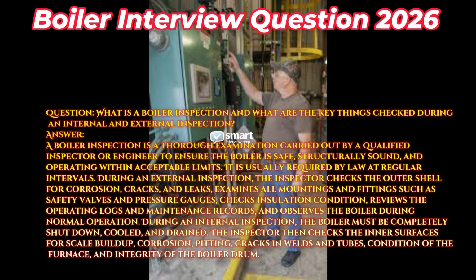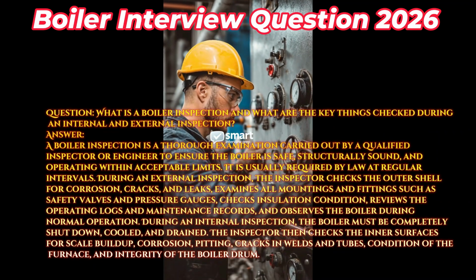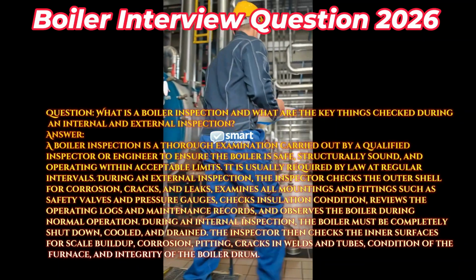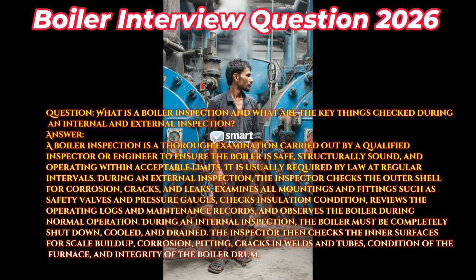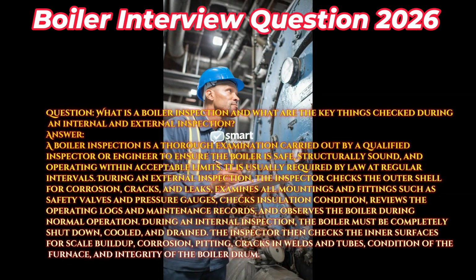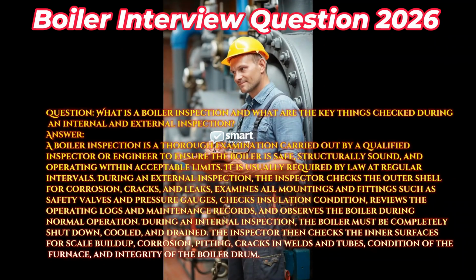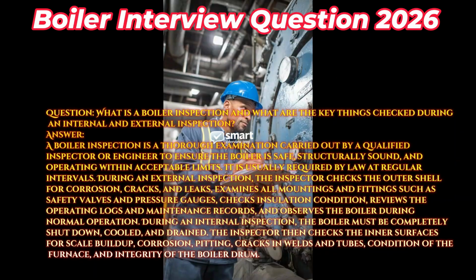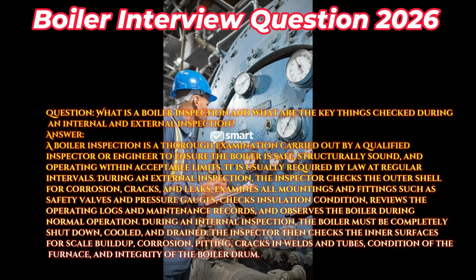During an external inspection, the inspector checks the outer shell for corrosion, cracks, and leaks, examines all mountings and fittings such as safety valves and pressure gauges, checks insulation condition, reviews the operating logs and maintenance records, and observes the boiler during normal operation. During an internal inspection, the boiler must be completely shut down, cooled, and drained. The inspector then checks the inner surfaces for scale buildup, corrosion, pitting, cracks in welds and tubes, condition of the furnace, and integrity of the boiler drum.